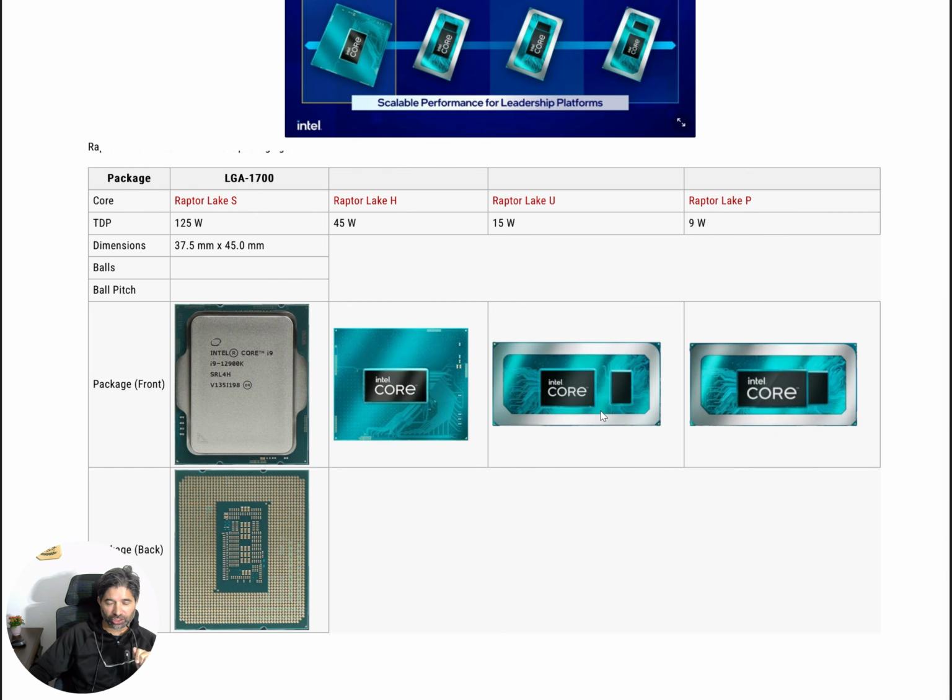There's a package tree. There's no interposer. By the way, about 2.5D and 3D ICs, I will talk about them, not in the STA series, but maybe some other series, and I'll give you an overview of that. So you can see that by having some of those dies done separately, probably the PCH on an older technology and the CPU on a later technology, you can combine them and get the benefit of cost as well as power.